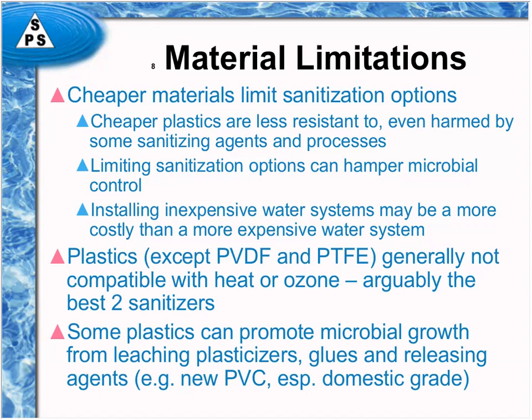Some of the plastics even promote microbial growth from plasticizers that are in the plastic leaching out to the surface of the plastic and then into the water. If you have a PVC system that's put together with glues instead of being heat welded, and a lot of plastics have releasing agents that are incorporated into them so they come free of the molds when they're being formed. Anyway, all of these materials are organic in nature and can serve as food.